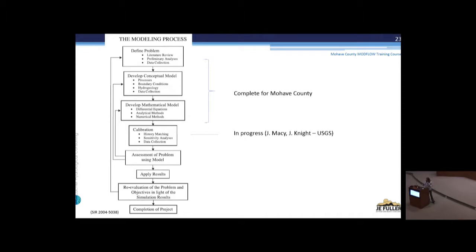A sensitivity analysis, and this means with MODFLOW, it's kind of like a machine where you can dial one knob at a time and see how that affects the input and output. It's kind of like you step on the accelerator in your car and you watch the needle move, or you put on the brakes and you watch it move the other way, or maybe you have some other alteration. You do something to the system and you watch it reflected in the output. And you keep doing that over and over again, and you adjust the parameters.